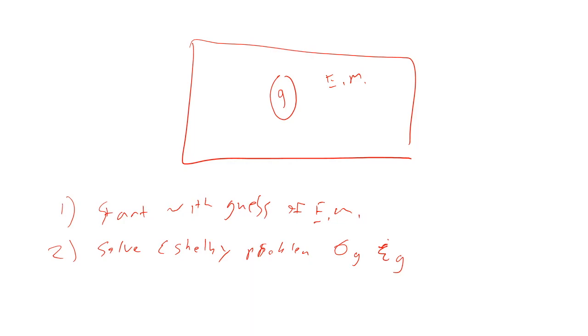Instead of an elastic modulus, we transform the problem so we have an instantaneous plastic modulus. So we solve it as a pseudo-nonlinear elastic problem where you've got this instantaneous tangent modulus. But that's a little too deep. I don't want to get lost in those kinds of details.